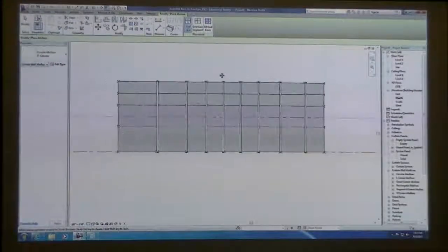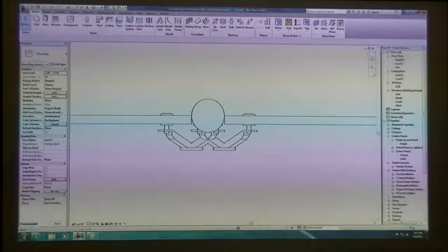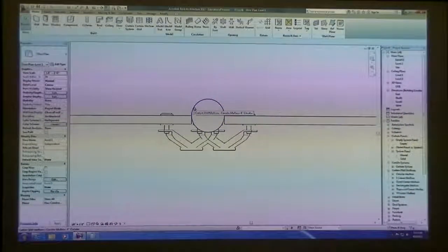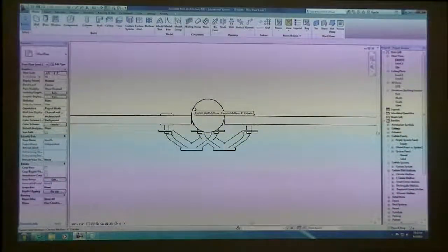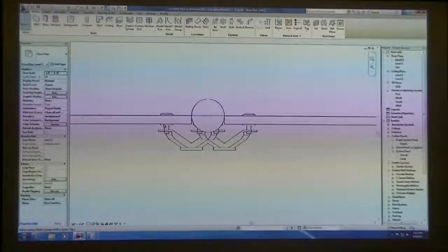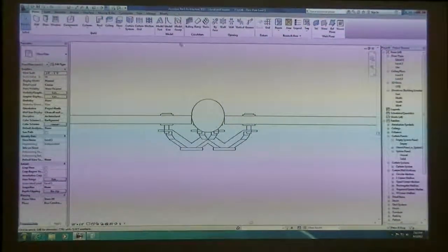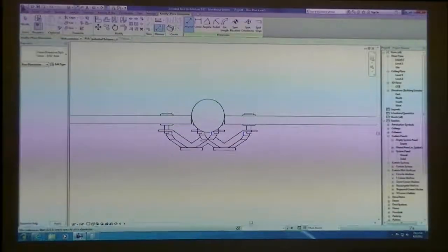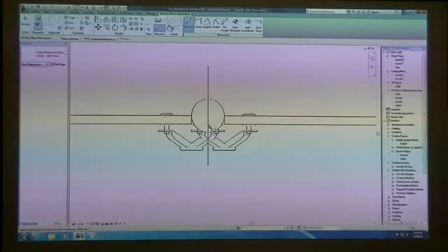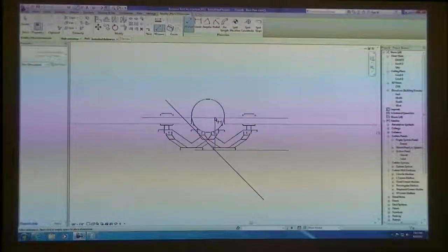What Revit does is, if we look at a floor plan view, it wants to place this as a mullion that's cutting the glass and leaving a space for the system. And so basically it's moving that reference line on either side of the column, or the mullion that we've placed. The next thing I want to do, though, before we fix this problem, is I also want to offset this circular column so that it's actually at the back face of the spider clip.